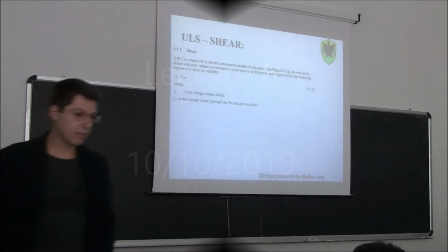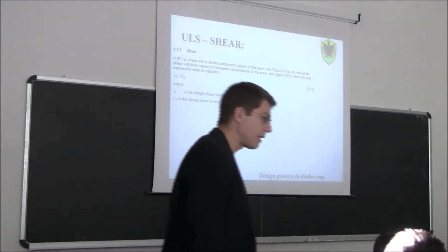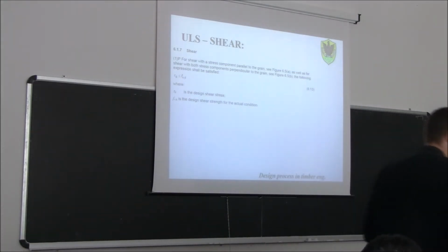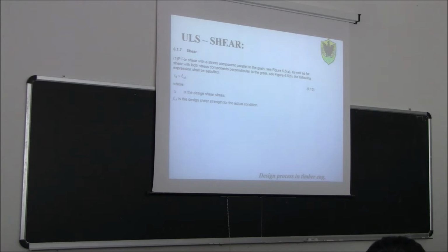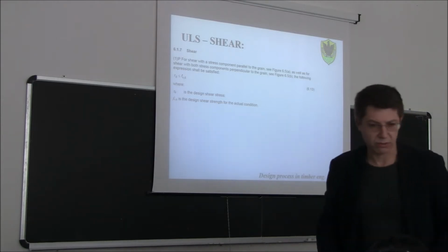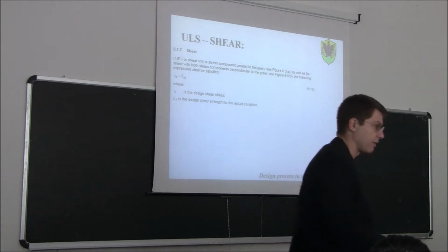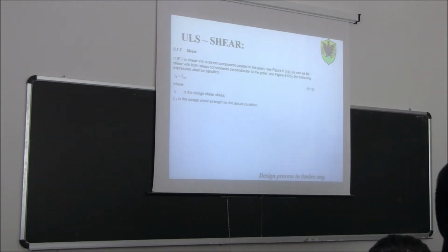Morning. After analyzing yesterday the problem of flexural buckling, which, as I said, is a very important problem for the bottom of the structure, we need always to keep in mind that if we have a compressed member, almost everything we will have to do also the flexural buckling check. It's not enough to do the compression strength in the plate, we also do the buckling.